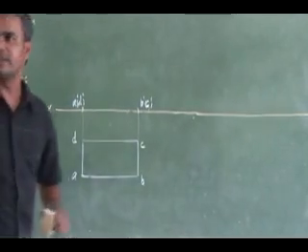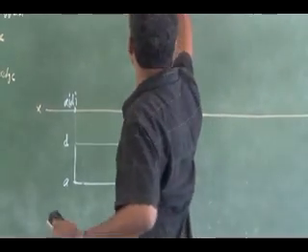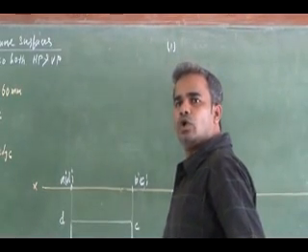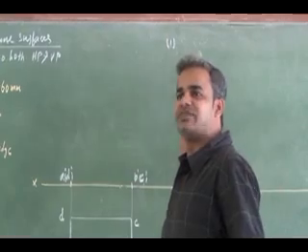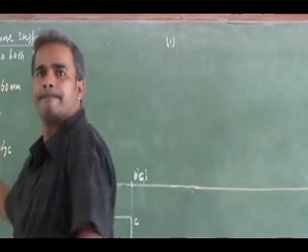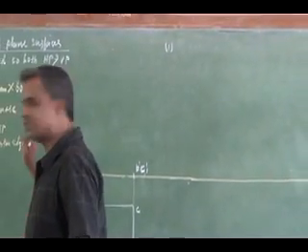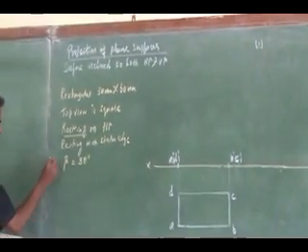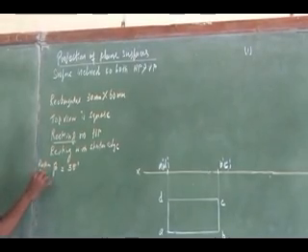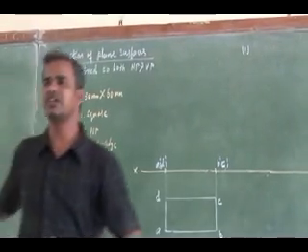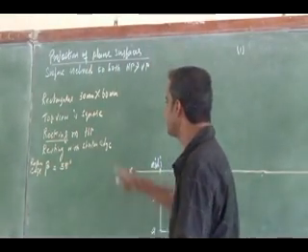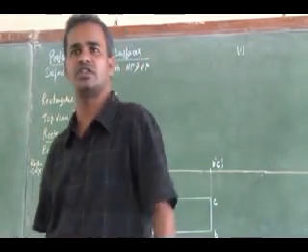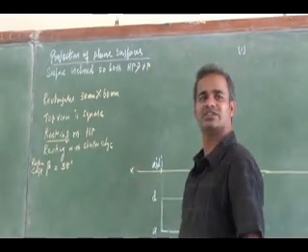Now I have to tilt it. In the second step, in the previous problems, which inclination did I tell you to use? You have to use the surface inclination. Do you have a surface inclination here? As far as this problem is concerned, you don't have the surface inclination. This is an edge inclination. Beta is nothing but the resting edge inclination. Surface inclination is missing in this problem. Instead of that, what is given? The top view is a square. Finally, it is asked, what is the inclination of the surface?